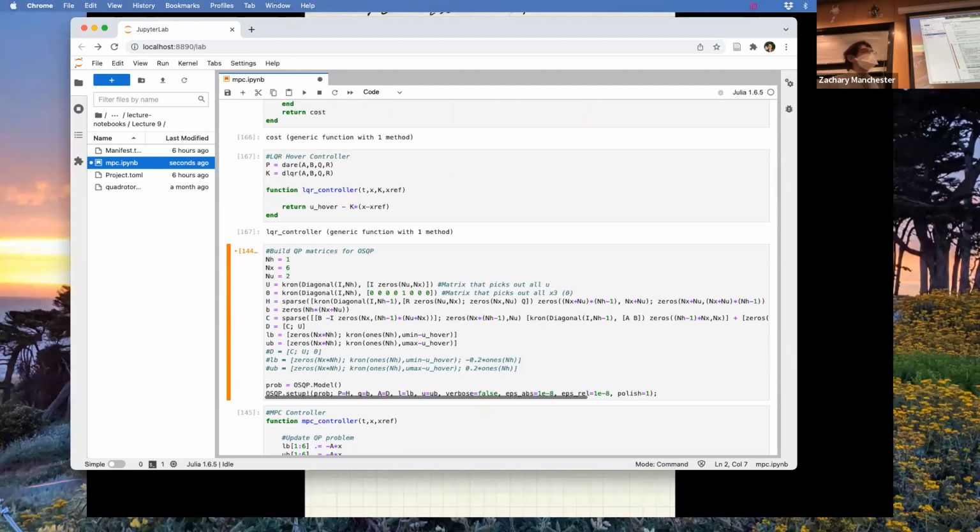Okay, now we're going to do the QP stuff. So I'm going to walk you through this a little bit. We're using an off-the-shelf QP solver for this called OSQP, which is state-of-the-art, a really fast QP solver that's very widely used in online MPC applications. It's on lots of robots. So here's what this looks like. This is the horizon. For comparison purposes, I'm going to set the horizon to 1 right now. As we just talked about, that should make it basically match LQR, right?